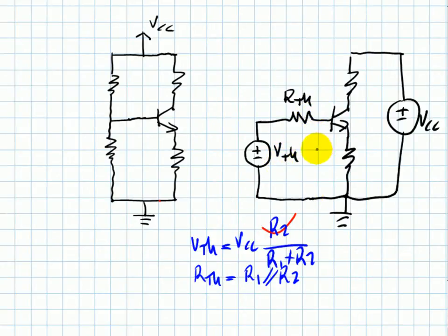This one. Why is this so good? Well, because finding the base current in this one, which will be IBQ in this circuit, is kind of easy. Check it out. This voltage is 0.7. It's known, 0.7 volts. We're assuming it's in linear operation. And then we say, the current here is going to be, in reality, beta plus 1 times the value of that base current, right?